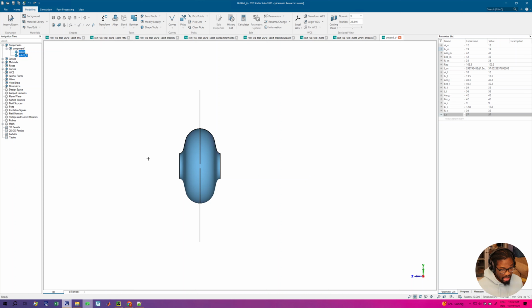So I can translate, and I want to translate this. Still, I want to center this. Okay, I'm going to translate this by LM, and I need, not translate, I should copy, and then I should be able to select the repetition factor. That's 2, 3. How many do I need on this side? Maybe 3. I think I may have to recenter it. Let's see.